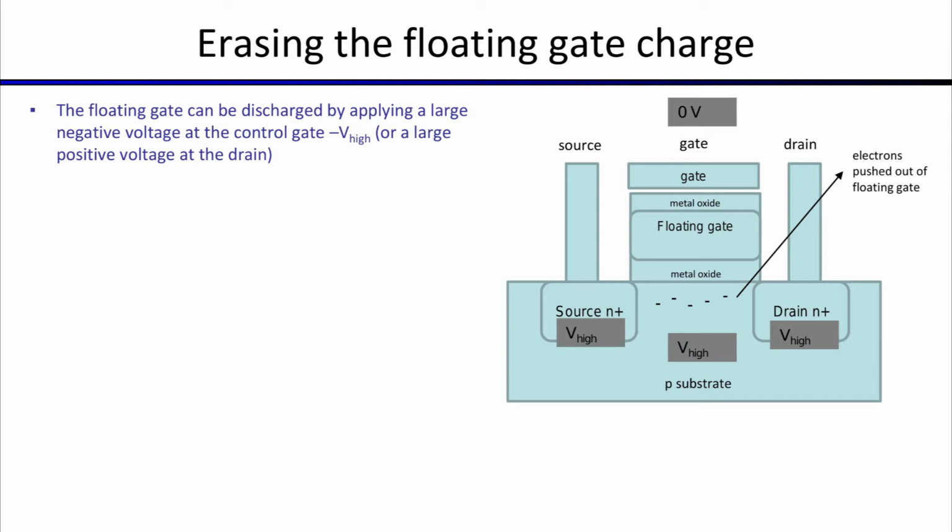And now, one more property to keep in mind is that there is a certain level of degradation that happens over the lifetime of write and erase cycles. And because of that, a floating gate charge can only be reliably read or written up to a certain number of cycles. And then you can't use that anymore because of charge leakage, or because the material that you have is not able to reliably store that level of charge.